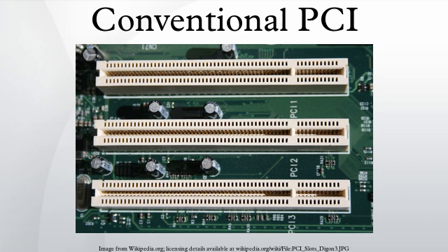The interrupt lines INTA through INTD are connected to all slots in different orders. Notes: IOPWR is +3.3 V or +5 V, depending on the backplane. The slots also have a ridge in one of two places which prevents insertion of cards that do not have the corresponding key notch, indicating support for that voltage standard. Universal cards have both key notches and use IOPWR to determine their I/O signal levels.